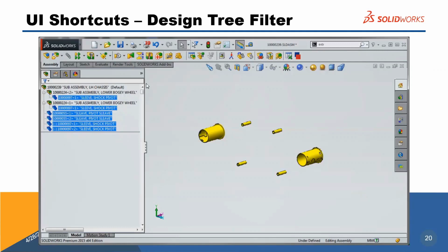Let's say, for example, you have been given the task of fixing a part that somebody else did. Not that that's never happened before, but one of the best ways of starting a little effort like that is to review the design tree and figure out what this person did and in the order in which they did it.